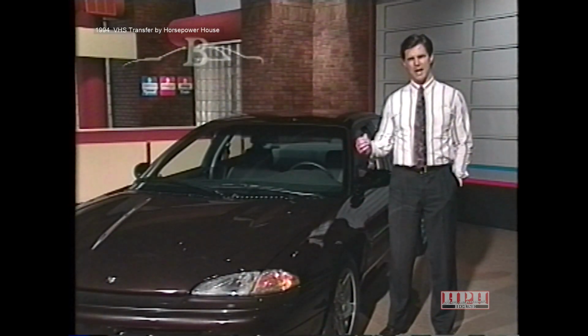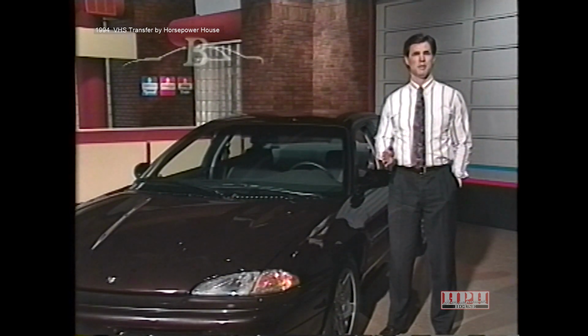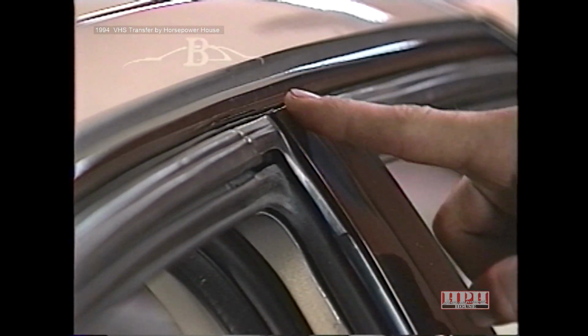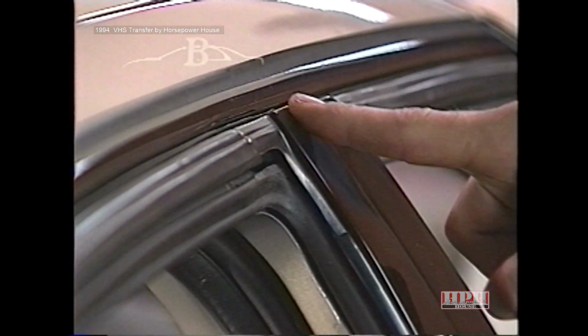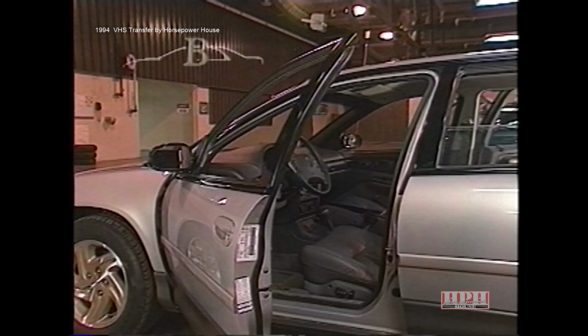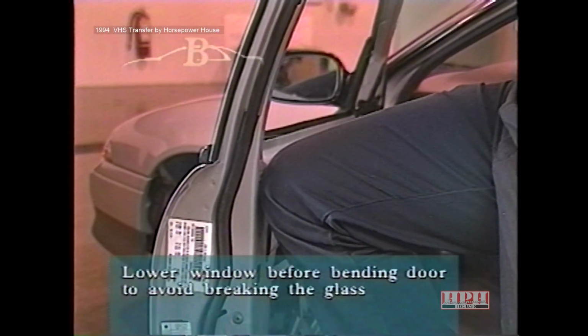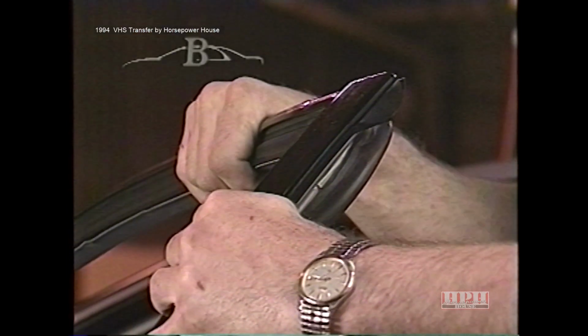232894. If wind noise is apparent around the top edge of the front door, this could be the result of a poor door fit. Check to make sure the top edge of the door is flush with the roof. If it is not, it can be easily corrected by slightly bending the top of the door inward. After lowering the window, put your knee to the inside of the door at the belt line and gently pull on the top of the door.